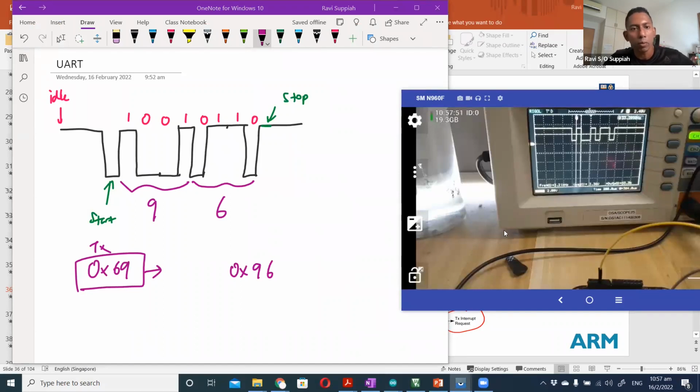This is quite important to note: whether the transmit module is transmitting most significant bit first or least significant bit first. When you expect to receive data, you also need to know which direction it will get shifted in. Sometimes the data is correct, but you thought it was in one direction when it was actually in the other, and then things don't work. That is why using a scope to check what is really happening can clear things up a bit.